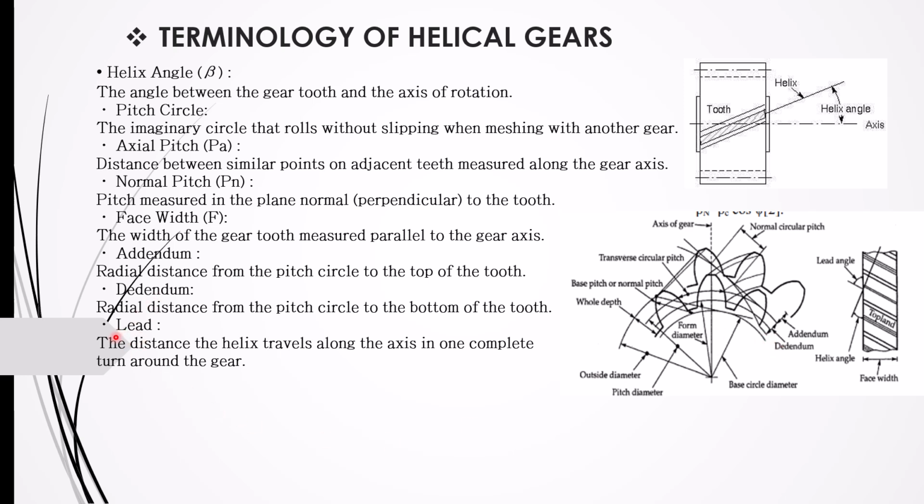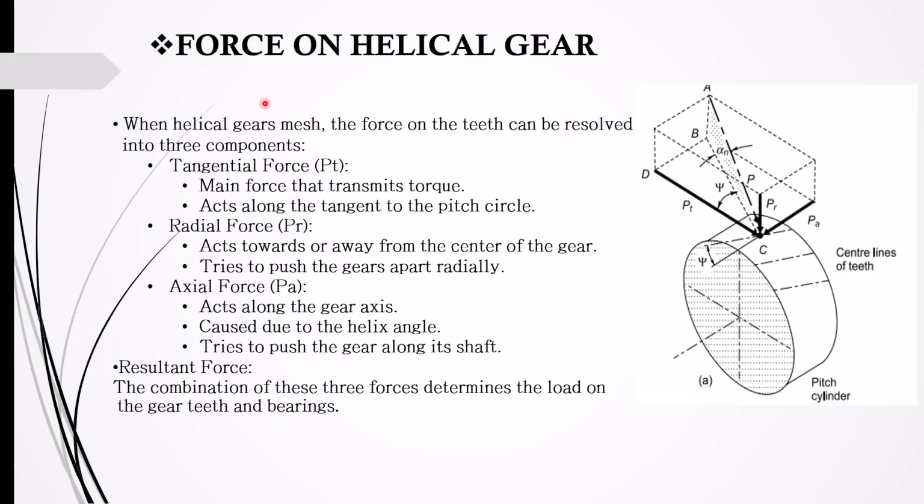Then lead. What is lead? The distance the helix travels along the axis in one complete turn around the gear is called as lead. Then forces on helical gear. There are three forces on helical gear. First of all is tangential force, then radial force, then axial force.